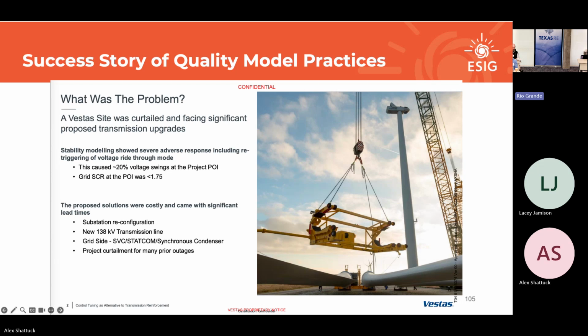So what was happening specifically, and this is one of those things I was talking about earlier, is the post-contingency SCR, if you want to use the metric, was 1.75. Low, right? We're well within the specialized tuning, and this shows why. All the other contingencies, fine. This was a system configuration where it got really weak, really radial for a first and a couple seconds.